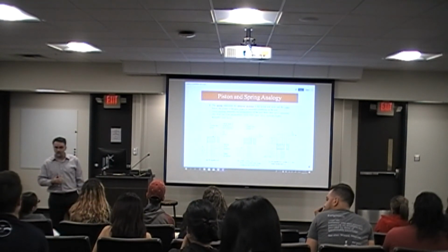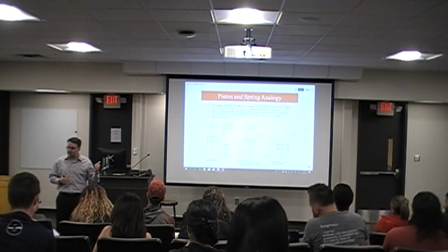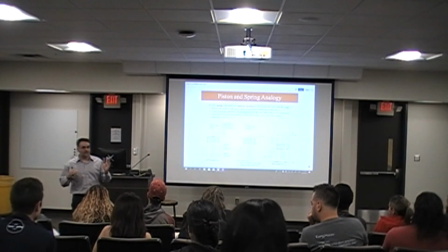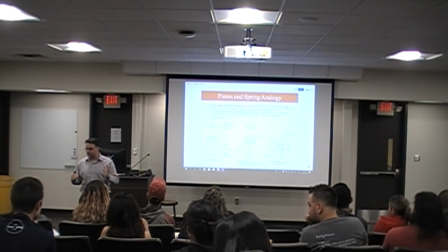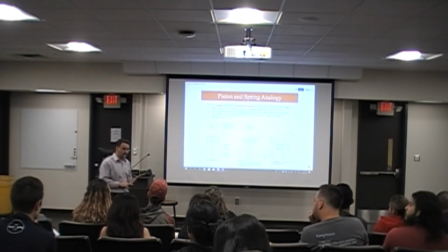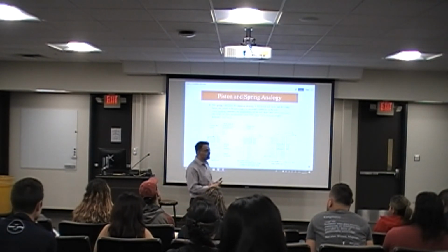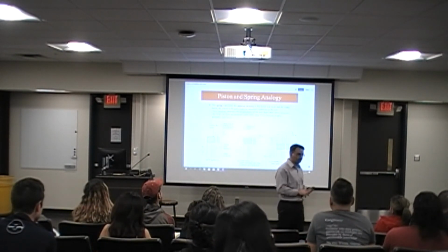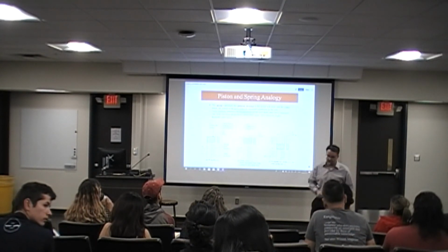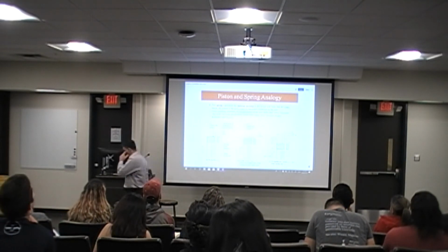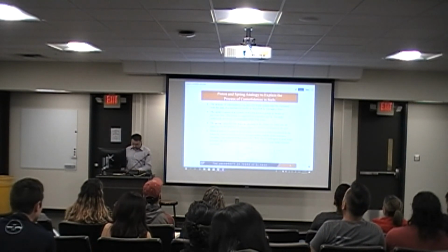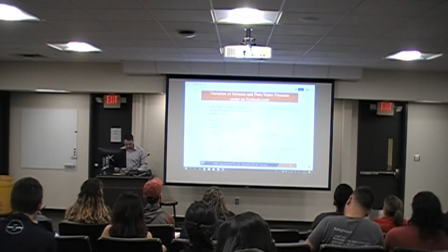And for this reason, from this point on, when we want to describe the settlement of soil associated with the discharge of water, we plot void ratio versus magnitude of the stresses, or effective stresses. So from this point on, everything has to do with the change in the void ratio. And the change in the void ratio has to do with the change in the volume of water that is discharged from the system. And we know that you apply the load, the water essentially escapes from the system, and there is a reduction of the void ratio with increase in the magnitude of the stresses. All right, so these are the descriptions that we have with respect to what we talked about.